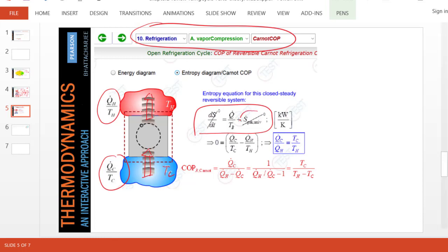And finally, there is entropy generation, which means what? Friction. Any type of friction, physical friction, mechanical friction that we all understand, thermal friction, which happens when heat transfers over a big temperature difference, electrical friction, when electricity goes over a voltage difference, whenever a gradient gets destroyed. Suppose you put a drop of ink in water, the ink will diffuse, the gradient of concentration is getting destroyed, which means there is entropy generation, there is friction, and these are called thermodynamic friction. When all kinds of friction is absent, suppose that your refrigeration system is ideal or reversible, then this is 0.